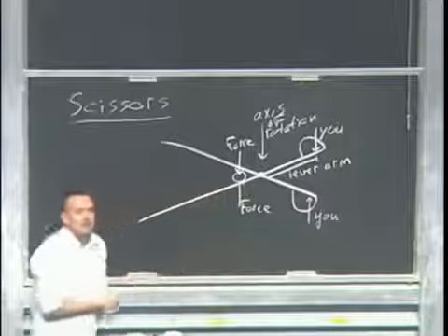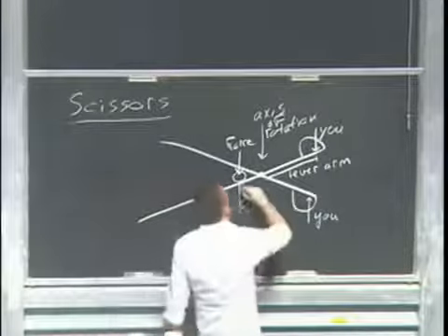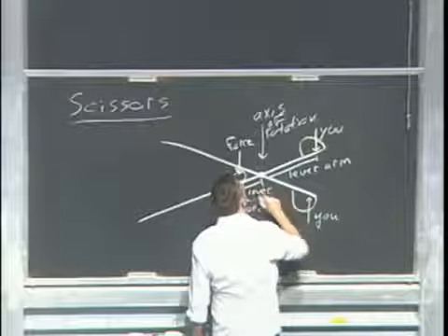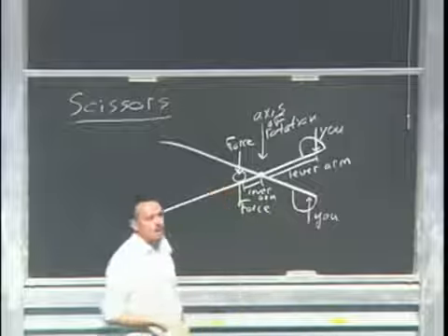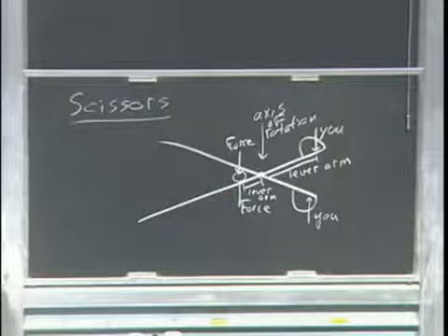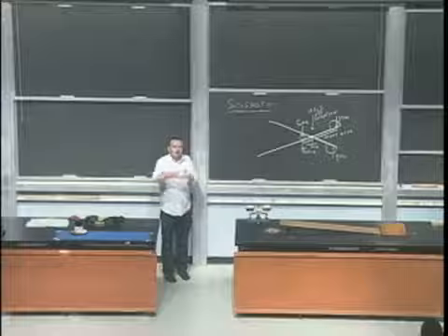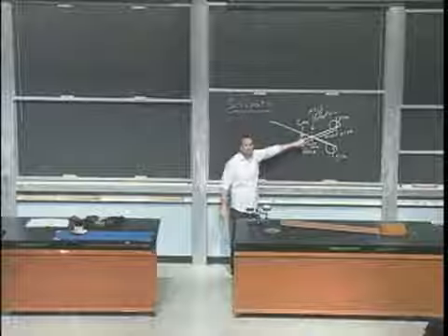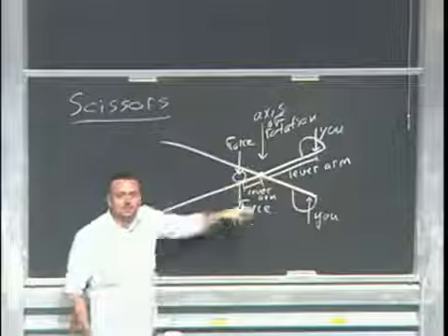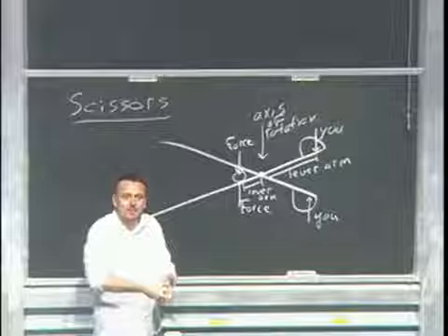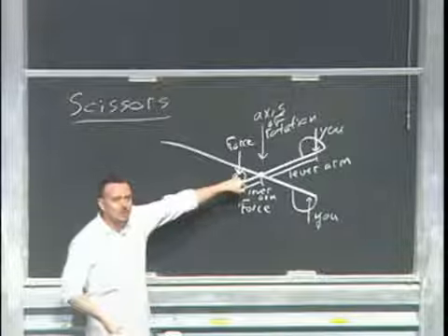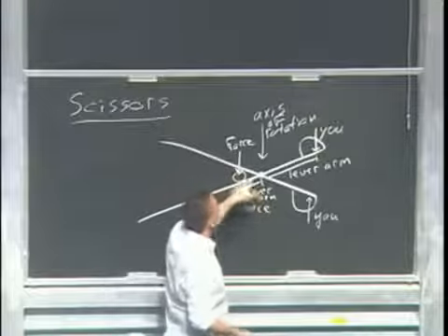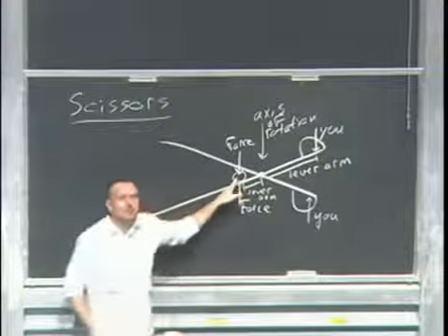That force is going to be acting with the little lever arm. So here is the lever arm on this side. And the point is, as you're squeezing those scissors closed, until this starts to give, there is no rotational acceleration, right? You're pushing down on it, it's pushing back until the point that it starts cutting through here. The fact that that is pushing back means that these are balanced, which means the torque on this side is the same as the torque on this side.